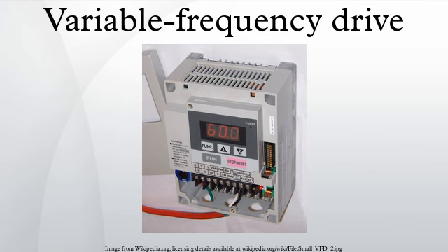Such rectifiers are referred to by various designations including active in-feed converter, active rectifier, IGBT supply unit, active front-end or four-quadrant operation. With PWM control and suitable input reactor, the AFE's AC line current waveform can be nearly sinusoidal. AFE inherently regenerates energy in four-quadrant mode from the DC side to the AC grid. Thus no braking resistor is needed and the efficiency of the drive is improved if the drive is frequently required to brake the motor. Two other harmonics mitigation techniques exploit use of passive or active filters connected to a common bus with at least one VFD branch load on the bus.